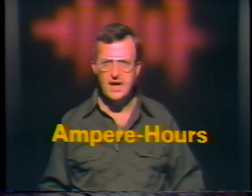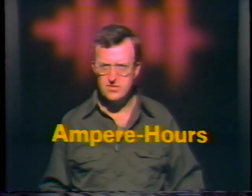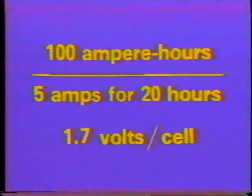Batteries are rated according to the amount of current they can supply for a given amount of time. The rating is usually given in ampere hours. For many storage batteries, the hours part of ampere hours is assumed to be 20 hours. So, if such a storage battery is rated at 100 ampere hours, it can supply 5 amperes for 20 hours before the voltage drops to the discharge level of about 1.7 volts per cell. As we saw earlier, with 1.7 volts per cell, a battery can't perform any useful work.